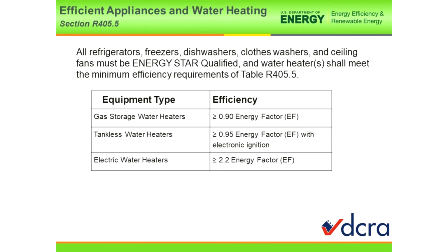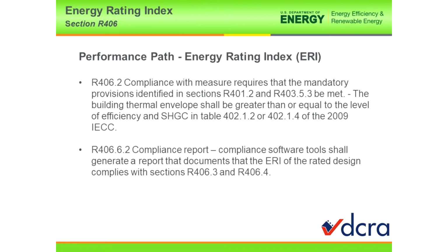Okay, and this is the setup for the water heater, right? Refrigerators, clothes washers, whatever, right? Gas storage water heater has to have an energy factor of greater than or equal to 0.90. Tankless water heaters, 0.95. And electric water heaters, 2.2 energy factor, okay? So that takes care of your enhanced additional packages, okay? Now we're going to talk about the ERI in a little bit more detail, but not a whole